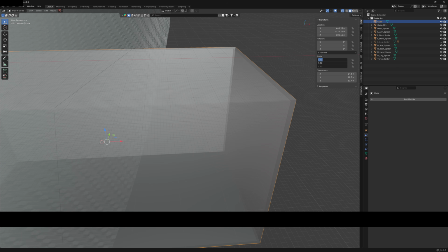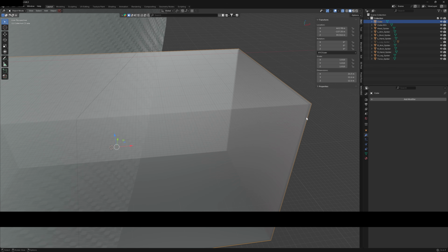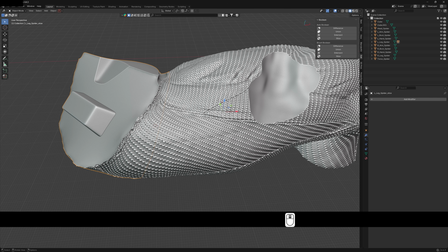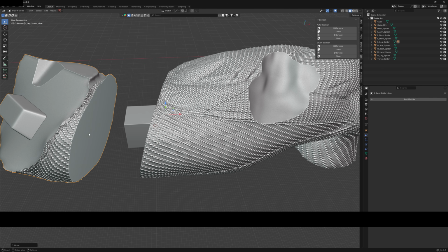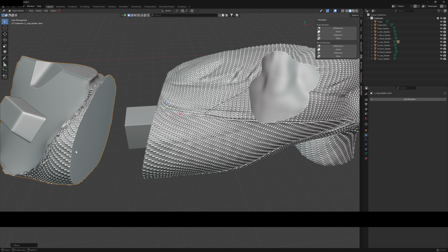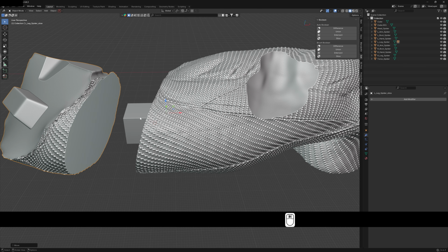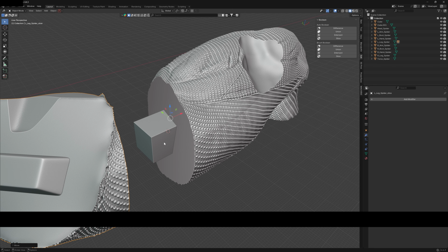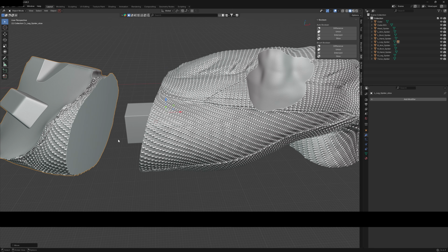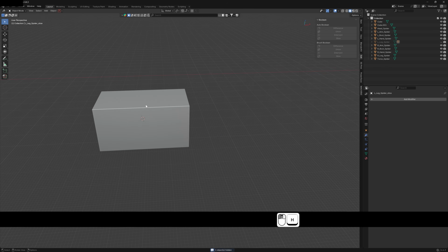It might be too big. This is going to be a bit trial and error, so 1.01. You can see the original cube just inside. The issue is, if I merely added a peg to go into the hole I create on this side, then you're going to ruin this flat contact point. So what I'm going to do is make a hole in both parts, and then you can print a connected dowel separately. So I'll just undo that. So what that means is I'm just going to hide the leg and hide that leg. So I've just got the cubes.